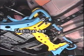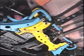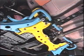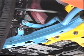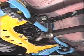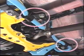The stabilizer bar is installed not only to reduce the vehicle's leaning caused by centrifugal force, but also to improve the driving force of the wheels. Usually, the ends of the stabilizer bar are connected to the left and right lower suspension arms. The center of the bar is mounted onto the frame, or part of the floor structure.